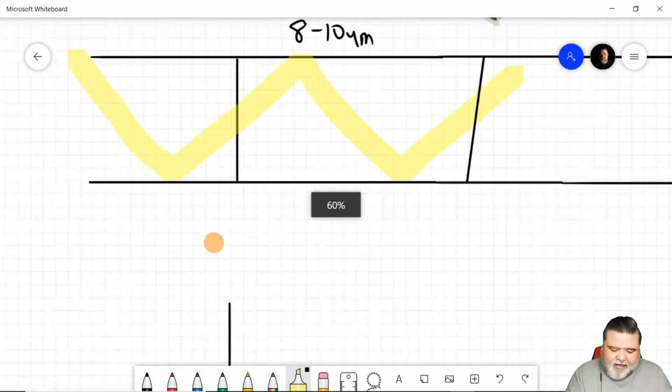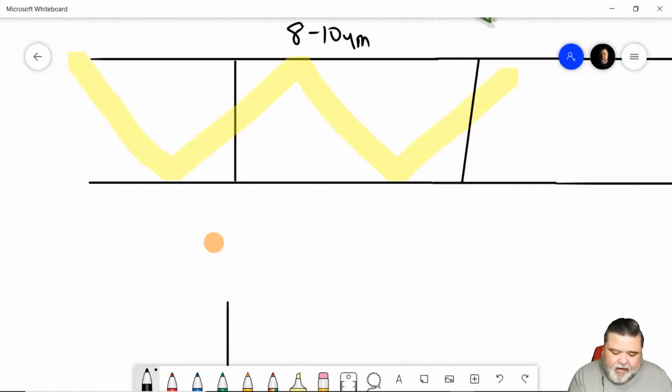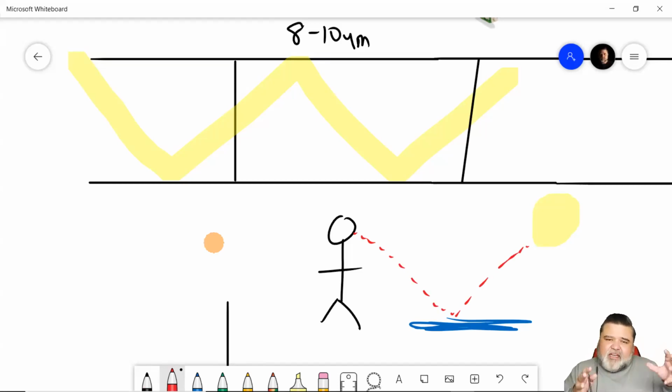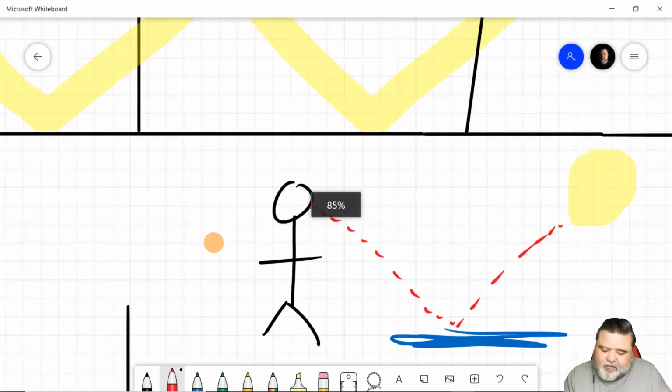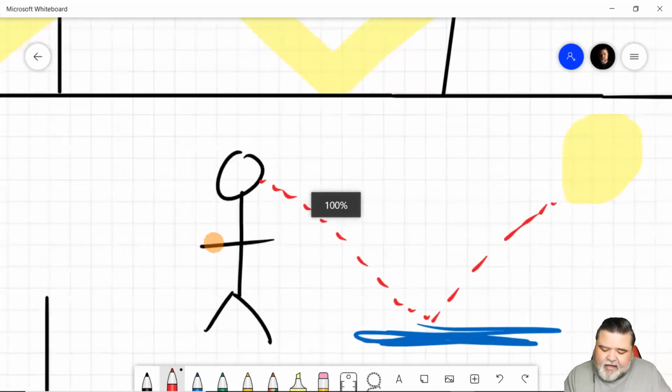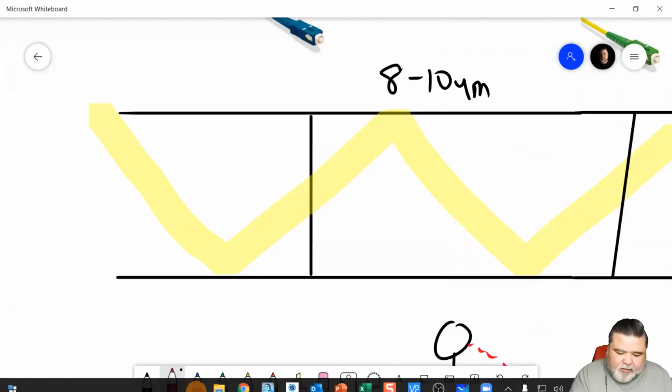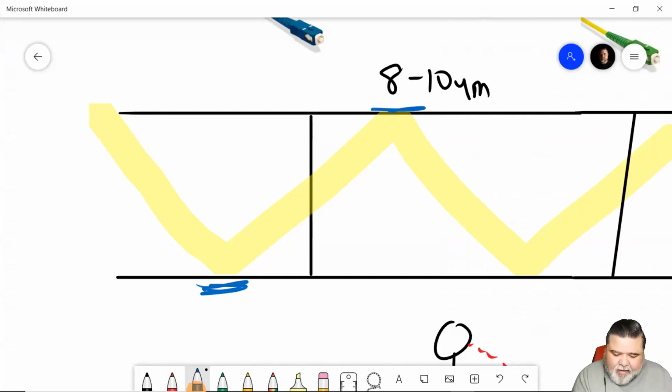And one way I like to explain it is if you're standing on the side of a lake or a pond, and those of you that have seen my presentation have seen this very remedial drawing from me. But essentially, when you're looking down at this smooth surface of water, it turns into a mirror finish, and you can see the trees and the sky. So for a very small section of the lake or the pond, when you look down at it, it reflects, and then you can see again the sun and the trees and the sky. That is roughly the angle that we need to maintain something called total internal reflection. That's how we keep the light within the core: we hit that one spot, and we maintain total internal reflection.